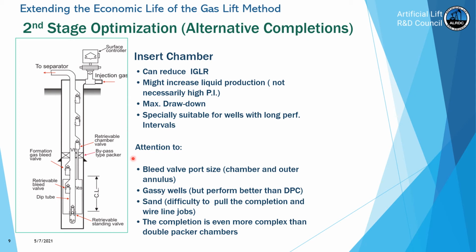Now, attention, you have to pay attention to the port size of this bleed valve and also of this bleed valve. So you now have two things to worry about. If you look at many old production operation books, you will not find this. They just didn't exist, and we found out the hard way that you have to have this port. This is very, very important. Otherwise, you will have problems. I'm going to talk more about this because this is very tricky when I explain insert accumulators.